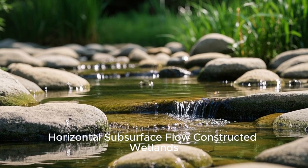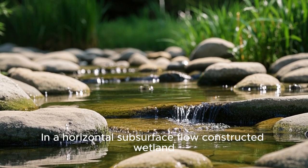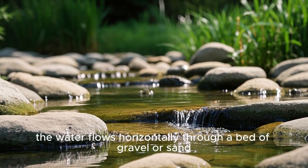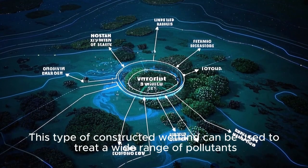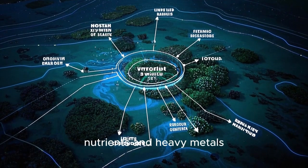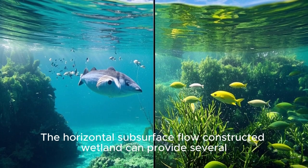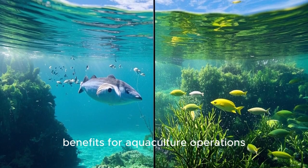Horizontal subsurface flow constructed wetlands. In a horizontal subsurface flow constructed wetland, the water flows horizontally through a bed of gravel or sand. This type of constructed wetland can be used to treat a wide range of pollutants, including organic matter, nutrients, and heavy metals. The horizontal subsurface flow constructed wetland can provide several benefits for aquaculture operations.